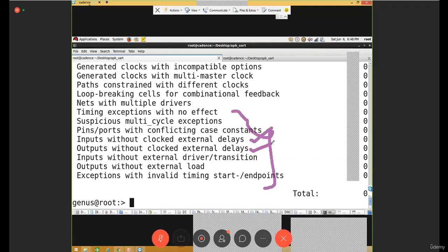So as a starting user, I think you guys might be just picking a logic of a counter or not. So this all exceptions is not so required for you. But when you take a complex design, like when a complete integrated circuit will come, this lint summary matters a lot because it is giving a usage of SDC file, and it is giving me the usage of the RTL file also. So it is compatible both for an RTL design engineer and a STA engineer or a PD engineer to go to the further process of implementation. So I think it is clear. The lint summary is clear.